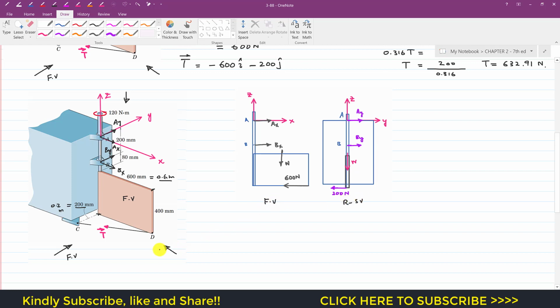Now if I draw the components of this T, since we found this Cartesian vector representation, T has minus 600 Newton, so we have the 600 Newton component in the negative x. If I represent that component, at point D we will have this 600 Newton component, and here at D we will have a 200 Newton component in the negative y.